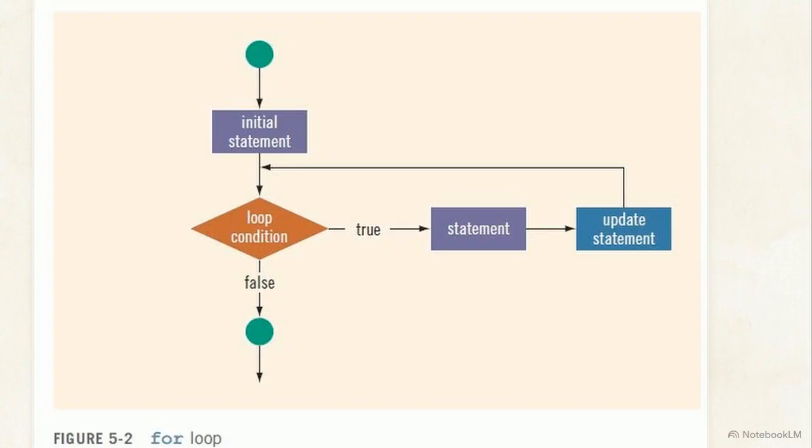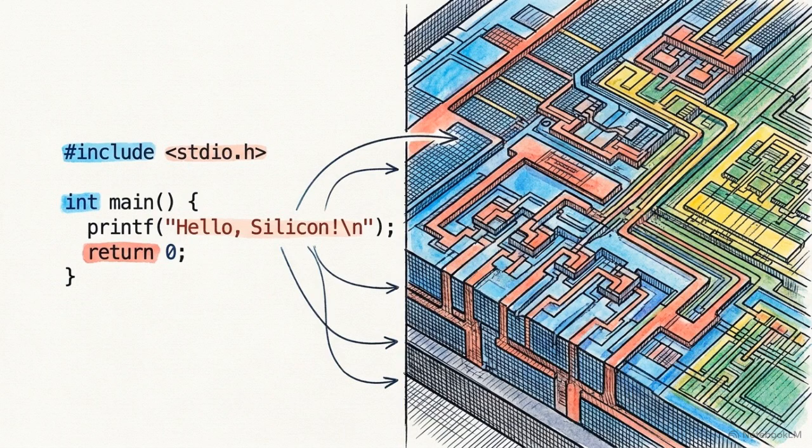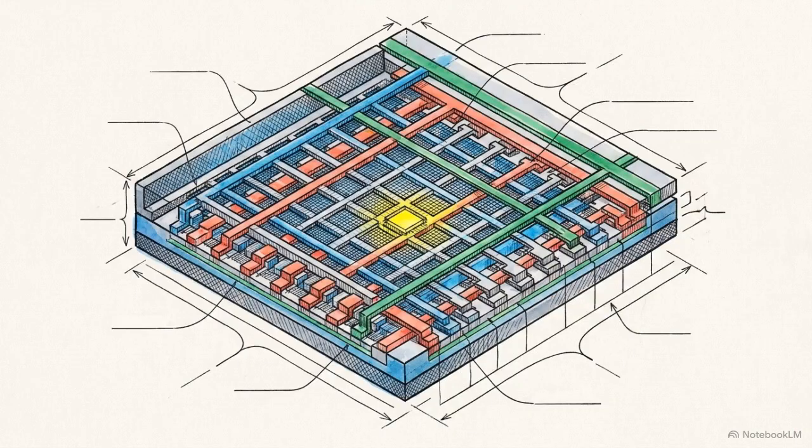To avoid this waste, assembly language requires developers to explicitly manipulate 8-bit hardware registers, like R2 seen here, keeping operations lean and fast. To retain the readability of C without sacrificing that raw efficiency, we have to adopt data types that align perfectly with the physical hardware. Successful 8051 programming requires treating memory as a scarce physical resource and using data types as strict allocation tools to manage it.